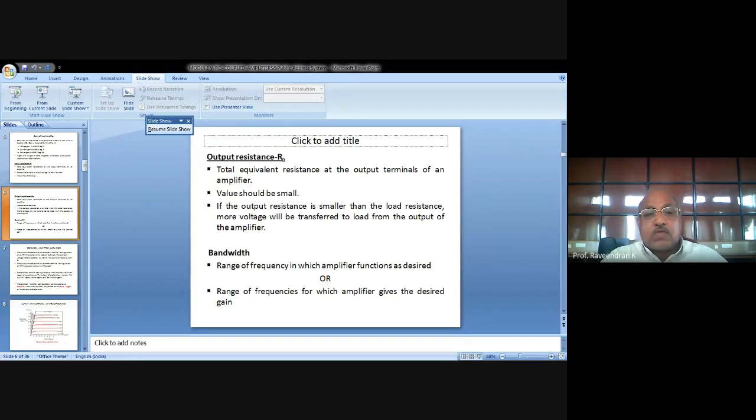So in that case, of course, the circuit must always be such that the temperature variation should not affect the operation of the transistor or the operating conditions of the transistor. That is the main purpose of the compensation technique. And this resistive biasing circuit will give compensating voltages and currents, maintaining the operating point always well within the active region of operation.